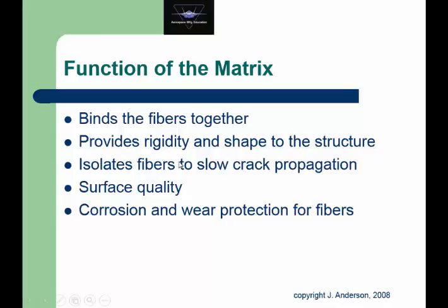So the function of the matrix is to bind the fibers together to hold them in place. It provides rigidity and shape to the structure by holding the fibers in place. It isolates fibers to slow crack propagation.